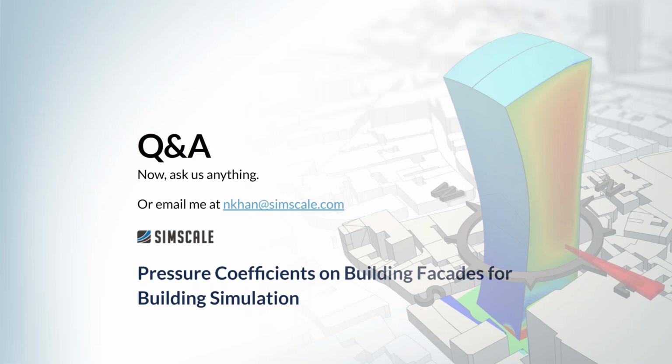We talk to a lot of people who work on all types of buildings: high-rise, domestic, industrial. We've got people modeling huge master plans and urban layouts, urban designers in SimScale. That works really well. Just an idea of what SimScale can do: we have an automated PWC tool. PWC stands for pedestrian wind comfort, and it's all transient analysis. What that means is we're modeling real-time wind, and if you imagine a building in a city center with a 500-meter radius around it, including all the context, we can drop that in and bring in the windrose for the location automatically.